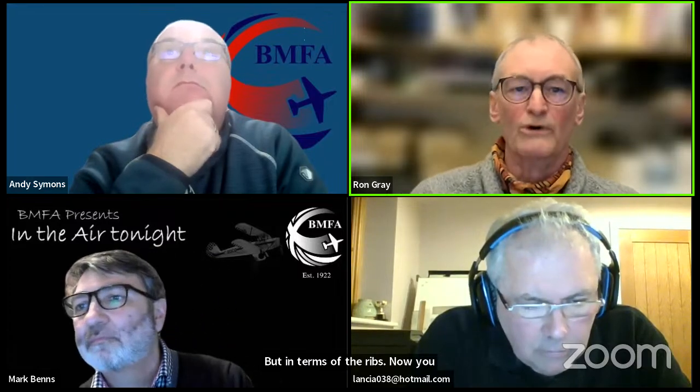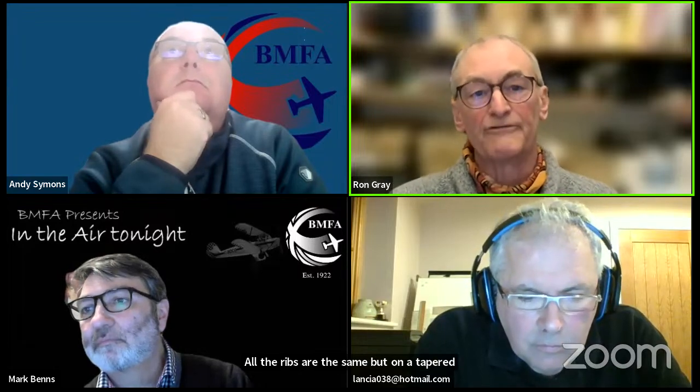The way you sweep it, you would have to draw the elliptical lines of the outer edge of the wing. And when you move the root rib to the tip rib, the constraints you're going to work within are the lines that you're sweeping along. They're the rails that you're sweeping along. But in terms of the ribs, mine's dead simple. All the ribs are the same. But on a tapered wing, all of those ribs are different.